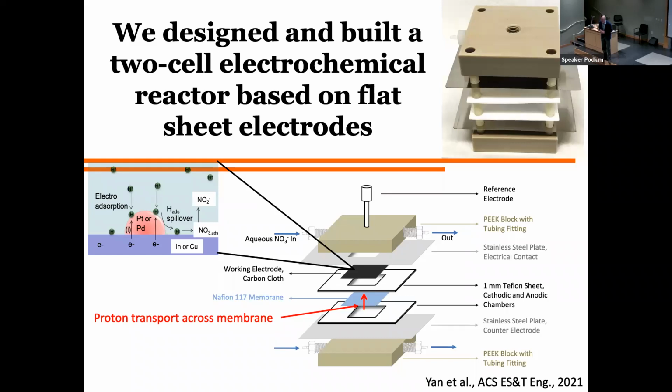Any pulse plating, so like a very short on cycle and then a longer off cycle? You're talking about the trickle bed reactor? No. Oh, in this case, we didn't have mass transfer limitations for this very small reactor, so we didn't try that. In the trickle bed reactor, when we varied the liquid to hydrogen flow rates, you have these different flow regimes that people have characterized in trickle bed reactors. You call it like your pulse flow regime. Then you've got your, I can't remember, there's like 4 names for them.